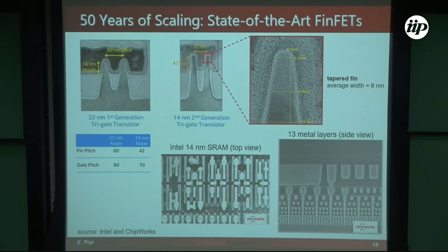And of course, this has to be done. Already these things have multi-layers. The computing layer is just there at the bottom. Everything else is just interconnects. So these things have like 13 layers of metals just for the interconnection. So it's pretty crazy already. But to me, this is 2D computing because the transistors are all at the bottom. There's no memory. There's nothing really useful on top, just wires, just boring wires.